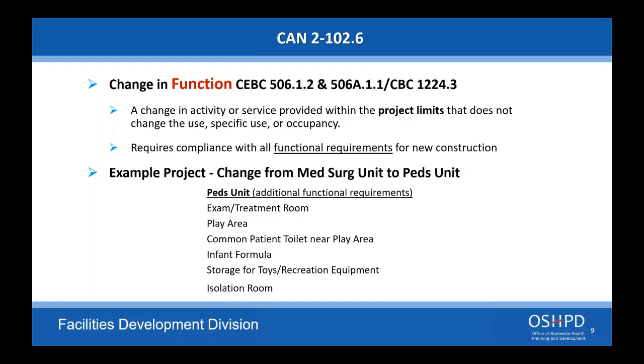If an HVAC unit needs to be lifted and re-anchored for a roof replacement project for proper flashing, does it need to be brought up to code within the re-roof project? No. You're allowed to remove and reinstall anything to its existing condition, unless it was existing non-compliant. You're allowed to put it back in to the code it was built under. That goes with any repair or maintenance.